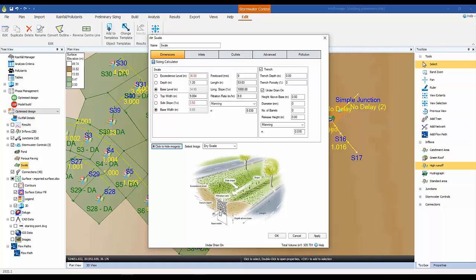And then we have perforated pipe here, so the water flows down from the gravel into the pipe and then flows out through the pipe. So there's essentially 3 different flow regimes going on here: the open flow in the swale itself, the flow through the gravel, and the flow through the pipe. And we have the ability to have interaction between these 3 flow regimes along the length of the pipe. And honestly, this is really groundbreaking for us. This ability to have flow moving from the gravel to the pipe to the swale all the way along its length is something that we haven't done before.